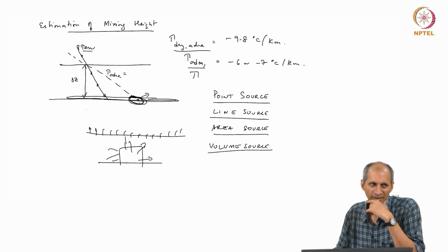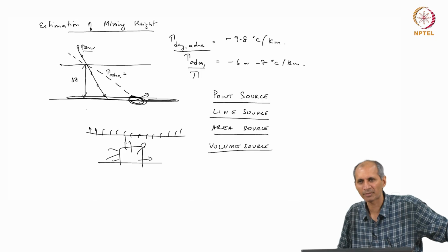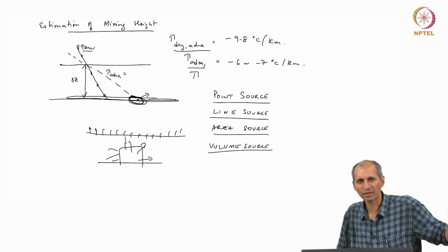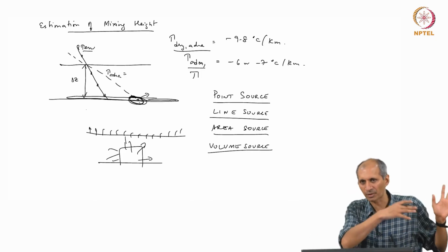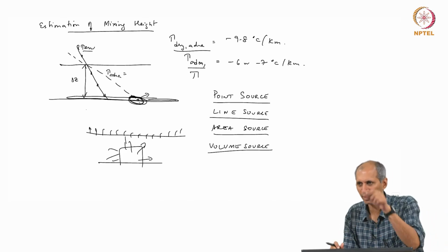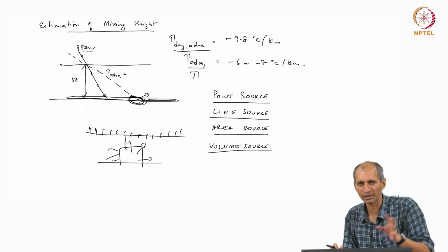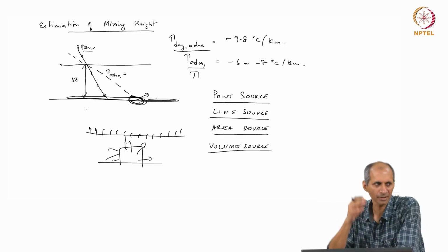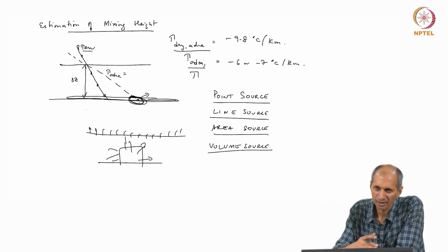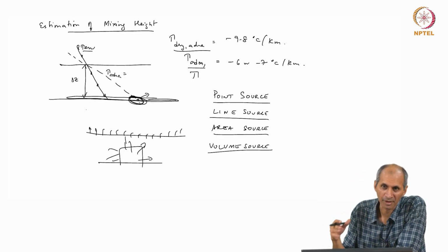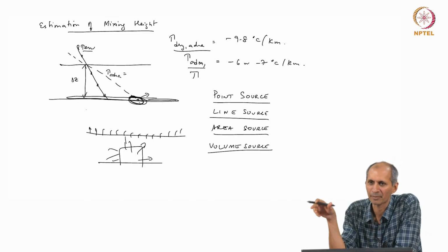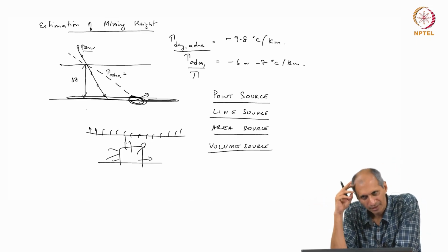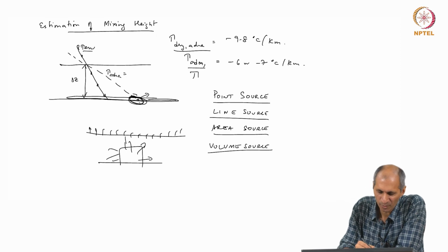For example, if I measure temperature on Sardar Patel Road, the main road outside our campus, and then I come inside and measure in a ground where there are no vehicles, the profile is going to be different. There will be a slight increase in temperature at the surface, but that is not to be considered as environment temperature, that is to be considered as the starting point of the adiabatic line. Okay.